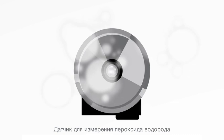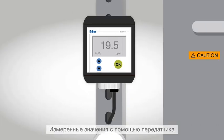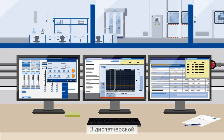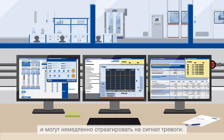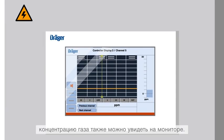A sensor for measuring hydrogen peroxide is installed in a stainless steel adapter. This ensures a defined measurement environment. The measured values, via a transmitter, are transferred to a controller for processing. In the last step, the measurements are visualized. In the technical control room, engineers can always view the hydrogen peroxide concentration and can respond to an alarm immediately. And right before entering the clean room, the gas concentration can also be viewed on a monitor.